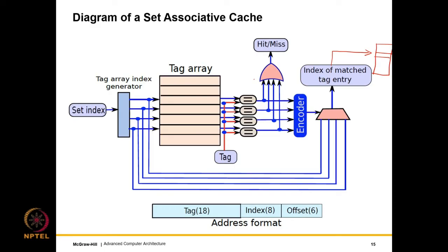We can use the same trick over here, which is that we can read the 4 tags in parallel, along with reading the 4 corresponding data array entries. This is a performance enhancing trick in the sense that we don't know which entry will match, if at all.